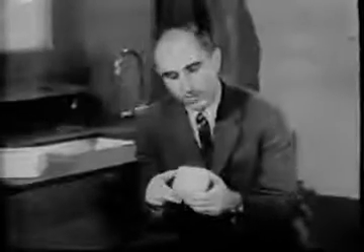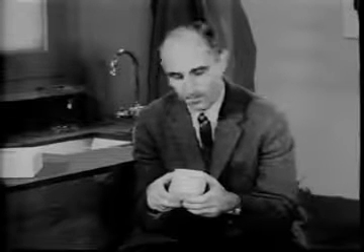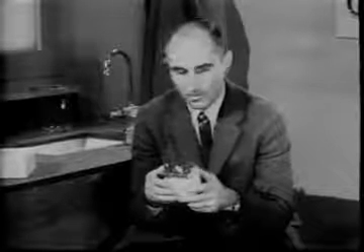Let us look at one of the faces of our particle. The greater the surface area, the greater the surface force. And so it is convenient to think in terms of the force per unit area. This ratio of force to area is called the stress. For instance, if we push with 5,000 dynes on this face having an area of 50 square centimeters, the average stress, or pressure, is 100 dynes per square centimeter. The distributed nature of the stress is indicated by these arrows all over the surface.